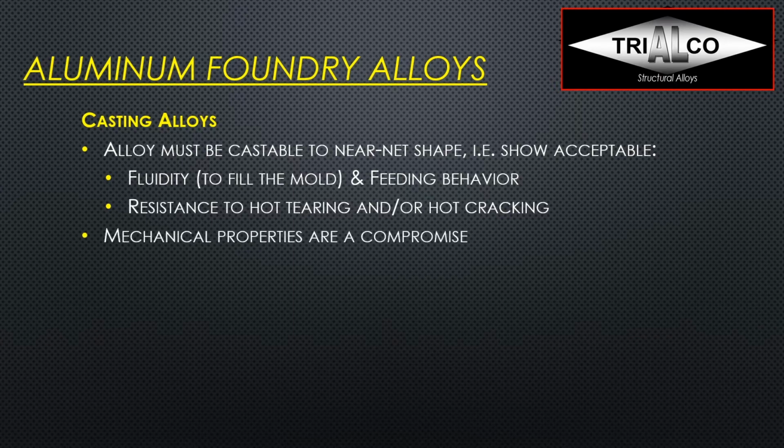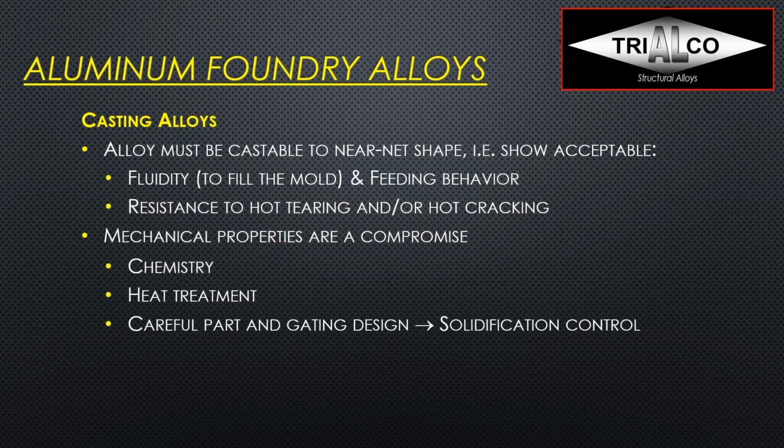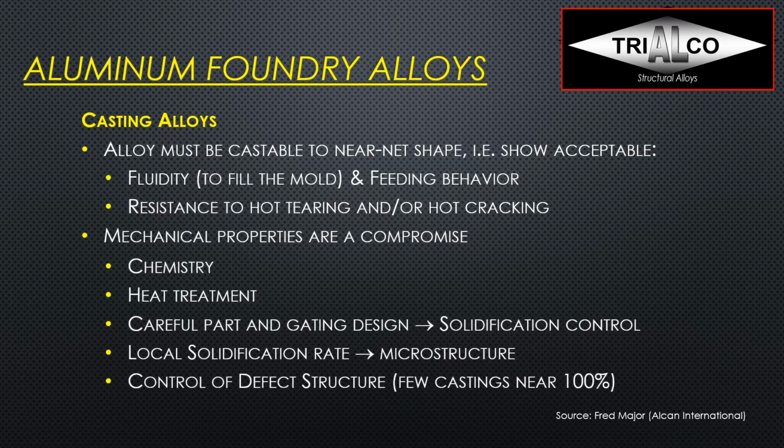My mechanical properties are really a compromise between chemistry and impurities, heat treatment, and careful part and gating design, so that means solidification control, and the local solidification rate, which gives me the microstructure. And we have seen that with a higher freezing rate, I will get a finer microstructure, and that will give me better properties, especially ductility. And then control of the defect structure, because very few castings are 100% perfect.